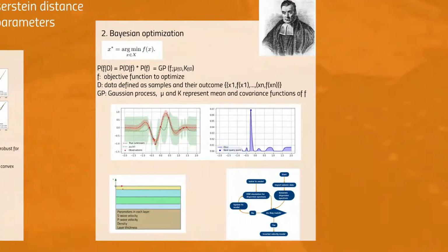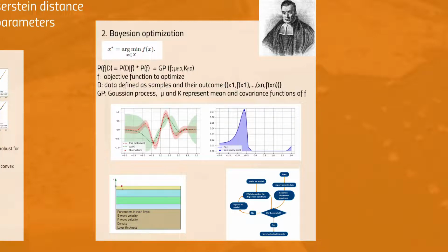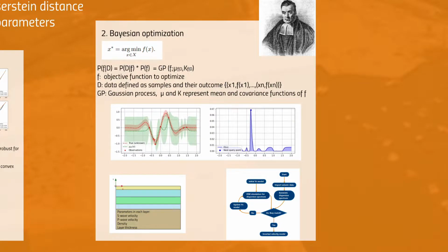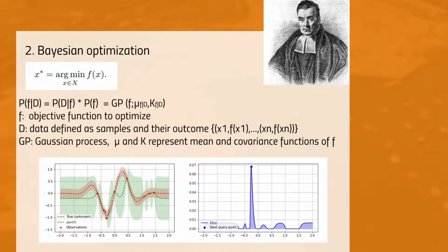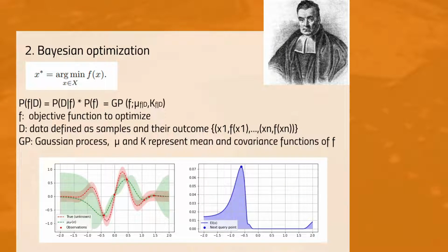After calculating the dispersion spectrum difference, we are going to back calculate the model parameters by minimizing the objective function f(x). This procedure is known as the inversion. Of course, we will not blindly search for the solution. Instead, the Bayesian optimization strategy is employed for inversion.